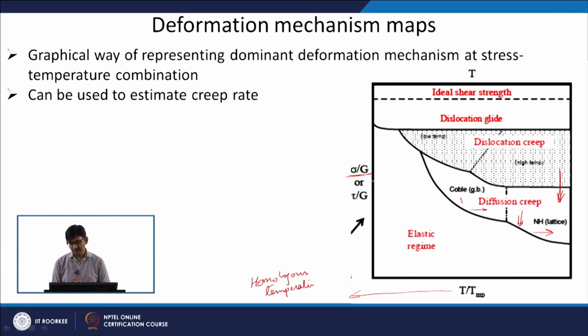Maybe I can go for another type of material for which these creep mechanisms are shifted to higher temperature, so my material is going to be safe at that particular temperature. For example, if my material is going to be exposed to this stress and this temperature, maybe I can choose another material for which all these mechanisms move toward high temperature. So, my operating service conditions are still within the elastic regime.